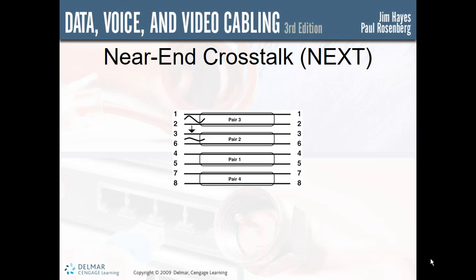Now, as stated earlier, at the connectors where crosstalk is most critical, the twist of each pair must be maintained to within a half an inch or 13 millimeters of the connection points to prevent undesirable reflections. If one expects consistent high-speed network performance, every component in the cable plant must be rated the same and installed precisely. Testing crosstalk is quite simple.